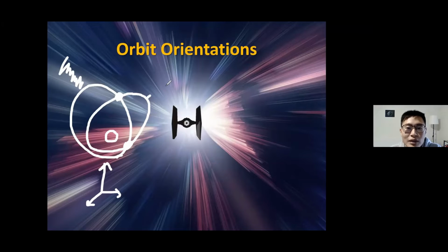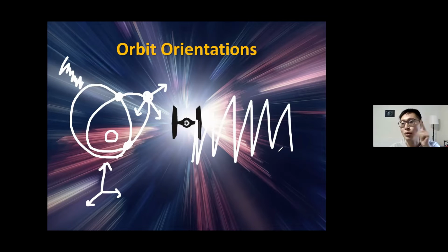If you actually go into the local reference frame of the satellite, let's say you are now sitting on the satellite and you're looking at it, from your perspective, what you will notice the other satellite in the other orbit doing when it has a different eccentricity is that it's just going up and down, up and down, from your perspective. So it makes it very difficult to chase and capture that satellite, right? Because in that moment, this guy is going to be going here, and while you could be going in some other direction, there's going to be some kind of a vertical motion, which makes docking very, very difficult if your eccentricities are not the same.